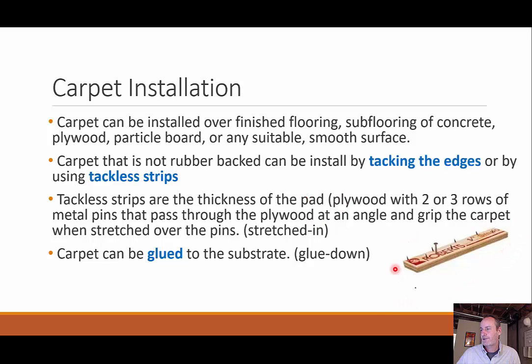Generally, I always think of these carpet strips. These are in either concrete or wood, where this one nail here is what's getting pounded into my subfloor, and then these little nails that are coming out, these tacks, are what's holding the carpet in place. So if you've ever seen this, it's like a knee kick, and you're kicking the carpet, stretching the carpet is what it's called, onto these tacks. So it's like a one-way thing, right? So the more you can stretch it, it'll just hold in place due to those tacks. So you imagine tack strips all around the perimeter of your carpet, stretching it into place.